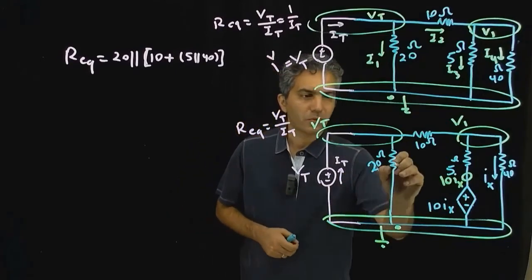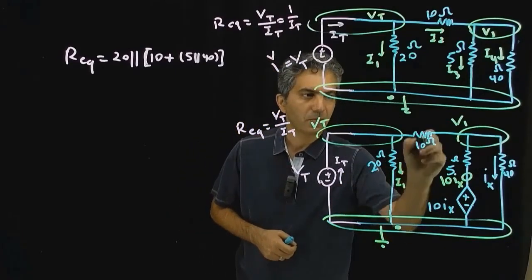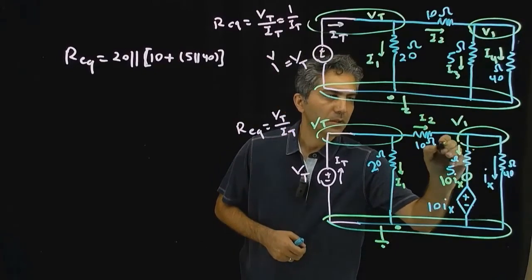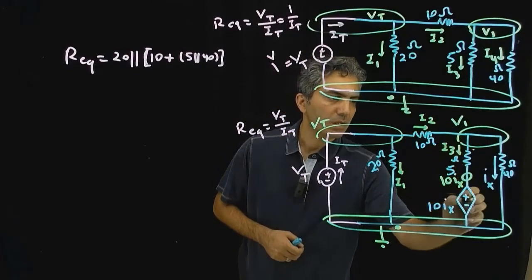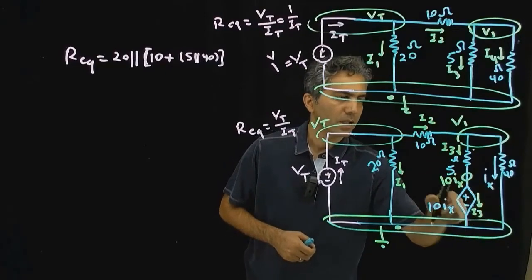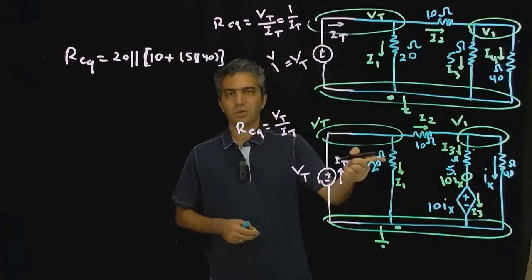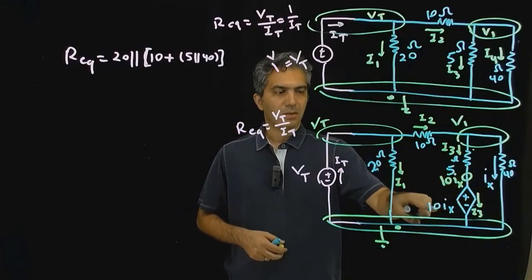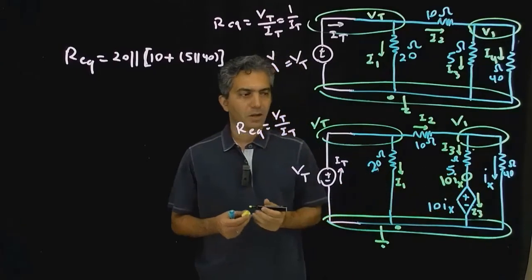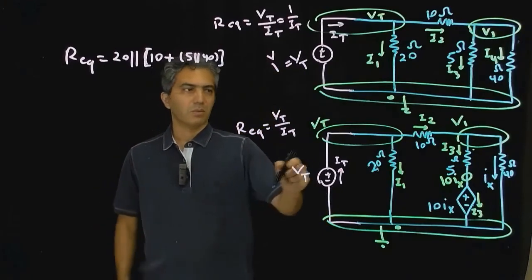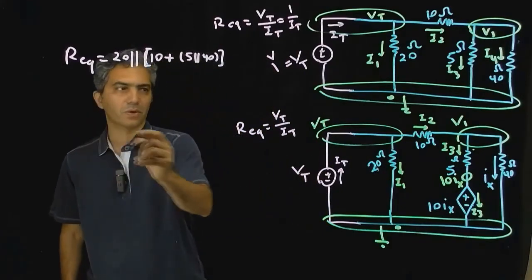With that, I move on to labeling the currents. That's I1. This is I2. This current, I'm going to assume it's I3. Same current passing through I3, KCL for that node. And finally, that's Ix. We don't change that because that is given by the problem, and this equation depends on that current. Once I'm done doing that, I can move on to writing my KCL equation for components.